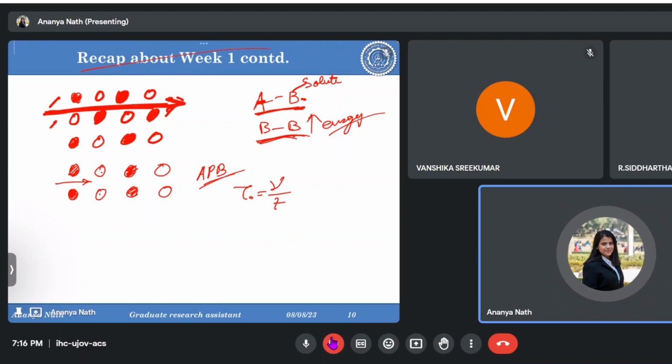When the temperature is high, solute will quickly move towards the dislocation and second phase will be precipitated. So if this is the dislocation, it's moving and the solute atom is jumping from one position to another. There will be a time when this dislocation moves much faster, when the temperature has increased.